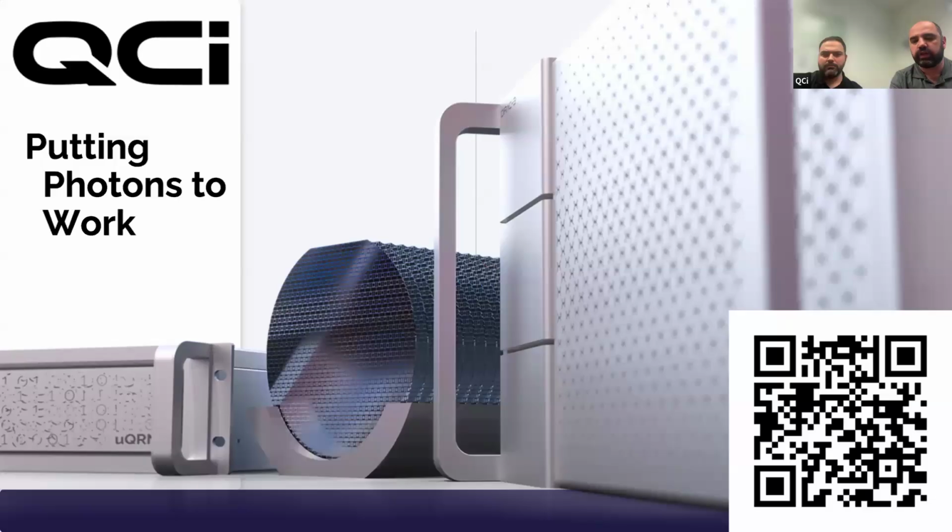Yeah, so I think that's a very interesting direction, which we haven't yet pursued, but we definitely intend to pursue. And I think the easiest way to do that is to grow PECVD nitride on top of a TFLN, and that gives you a very good path towards hybrid integration. And we are in discussions with some partners as to how to do that. But we don't have any results that we can share at the moment.